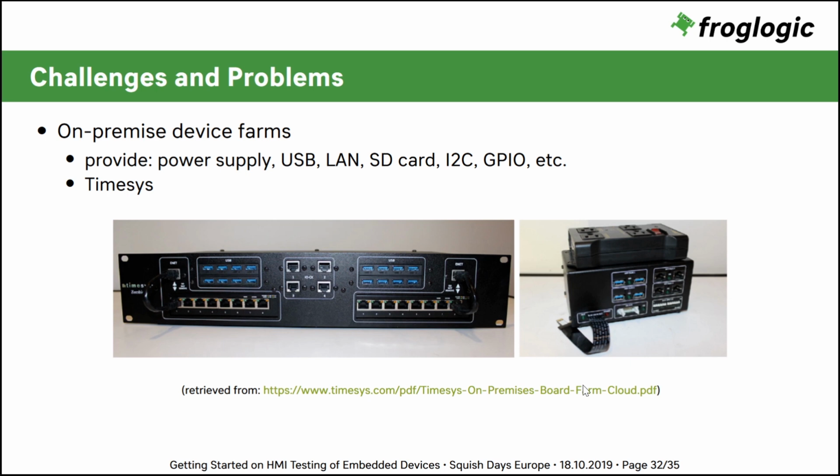As you can see here, you can even have one virtual micro SD card, so that from your test scripts you can change the SD card or the operating system image and the application on your device before you turn it on, and in that way you can support multiple scenarios.